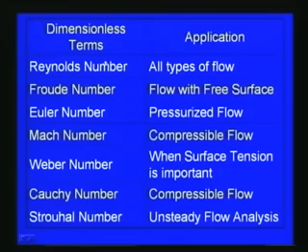So, first one is the Reynolds number. As we have seen, this number gives a classification with respect to laminar and turbulent flow, and it is used in all fluid mechanics problems, but especially when we deal with closed conduit flows like pipe flow, we directly define the Reynolds number, and then with respect to that we classify, and open channel flow also we can utilize the Reynolds number.